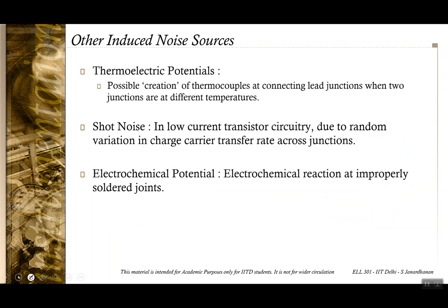Going further, these are sources of small spurious potentials. Like in a thermocouple, you can have thermoelectric potential, that spurious thermoelectric potential caused due to unintentional thermocouples being formed at different leads.